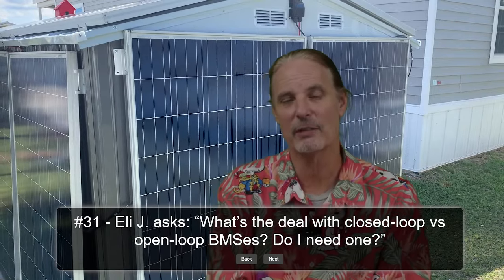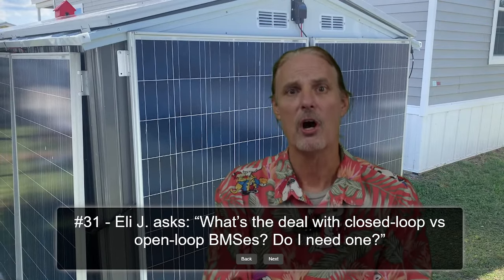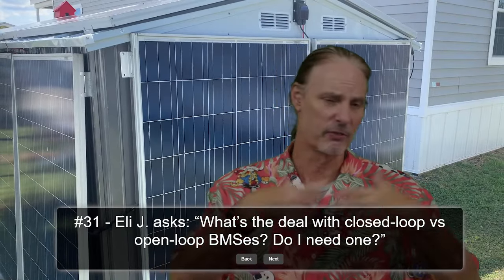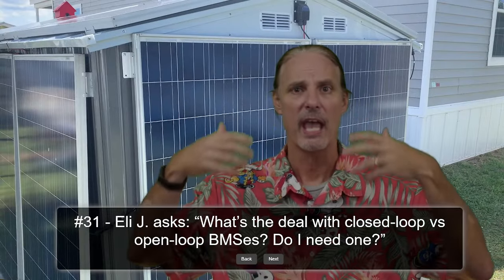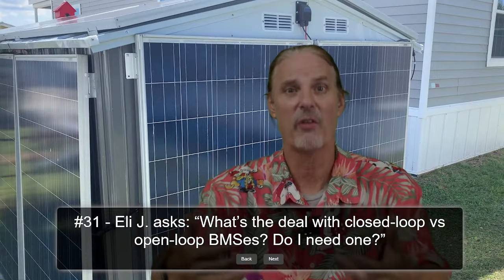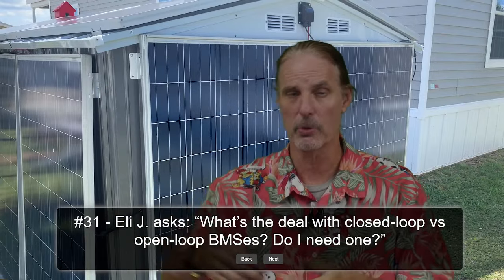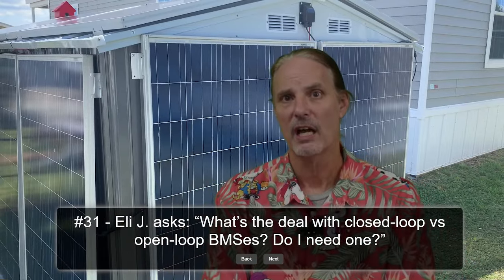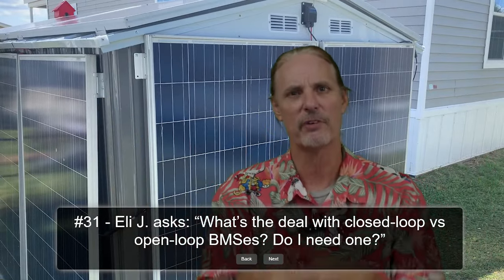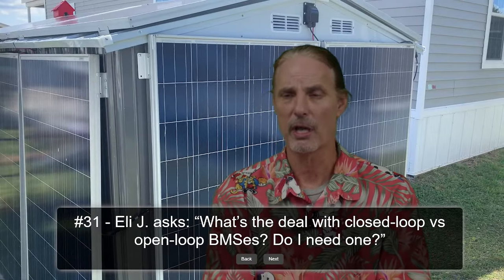And then they decided that it was important that this be used to communicate with the inverter about what is going on with the battery, and how much of a charge it can take. If you've got 3 batteries running and they're all allowed to take in a maximum charge, then it could tell the inverter, send me all the power you've got up to the amount that my batteries can support. If one of them says, hey, look, I've had enough, then it can also tell the inverter, hey, slow down a little bit. You're already 2/3 of the way there. You don't need to push so hard.